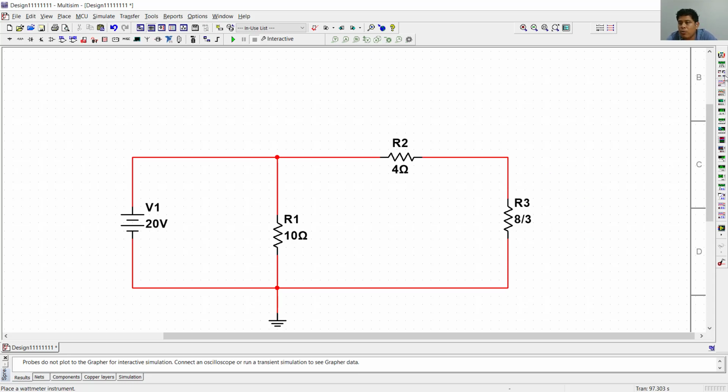And now I'll use the new tool here that is called wattmeter. I just go to the right of these elements here, and it's the first, second, third tool. So I'll click on it, and here it goes. This is the wattmeter. If you notice, the wattmeter has voltage and it has current.